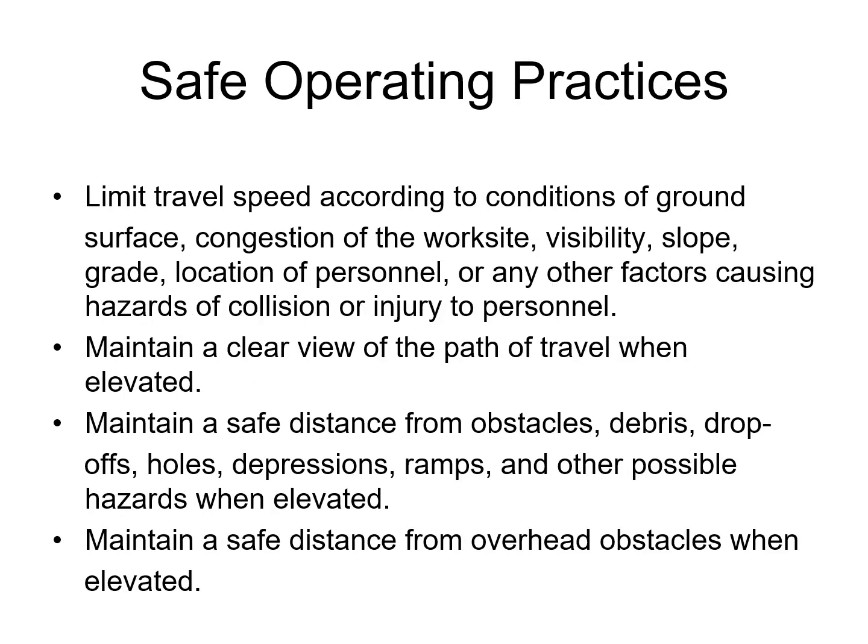Safe operating practices continued. We want to limit travel speed according to the conditions of the ground surface, congestion of the work site, visibility, slope, location of personnel, or any other factors causing hazards of collision or injury to personnel. Maintain a clear view of path of travel when elevated. Maintain a safe distance from obstacles, debris, drop-offs, holes, depressions, ramps, and other possible hazards when elevated. Maintain a safe distance from overhead obstacles when elevated.